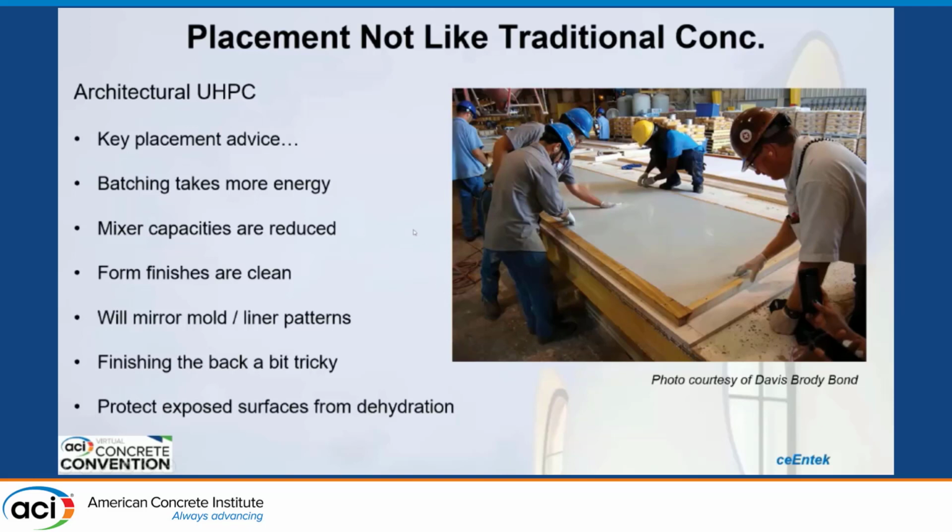There are some mixes out there where you can use drum mixers, but traditionally most UHPCs need a high shear type mixer that can put a lot of energy into the mix. The finish on the face of the form is going to be very, very clean, very smooth, a very precise reflection of whatever the form liner is, or the form that you're casting into. It will mirror the face of that form very, very accurately.